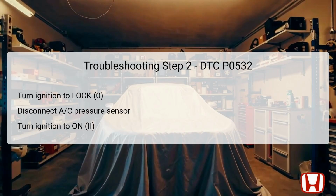Upon confirming a failure in the first step, you will proceed to determine the possible failure area of the system. Start by turning the ignition switch to the LOCK (0) position, ensuring all electronic systems are offline. Next, disconnect the AC pressure sensor by removing its 3P connector, which is essential to isolate the component under testing conditions. With the sensor disconnected, turn the ignition switch to ON (II) to power the system without starting the engine.